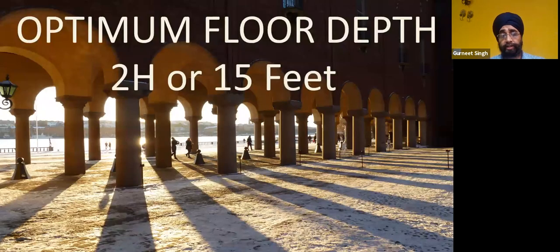The very first strategy, as an architect or as a designer or as a client, or even if you are buying a building or leasing out a building as a facility manager, is to see the floor depth of that building. So the very first strategy is to optimize the floor depth so that you have maximum floor area having good daylighting. And what is the thumb rule?